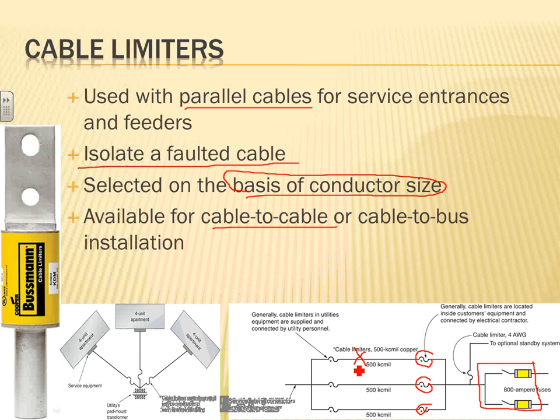Now the question would be, what happens then? Aren't you going to overload the others, right? That's the first thing that would happen. If the load is supposed to be carried by 3 sets and you interrupted 1 set, the other 2 sets will carry the load. Now, knowing that the load factor will be, like I said, from 33 to 66 percent of any power system, this will cover a lot of applications for you. It will contribute to the survivability of your power system, basically.